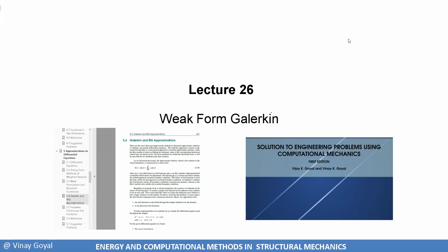In the Rayleigh-Ritz method, we make sure that the approximation is sufficiently differentiable in the functional, basically sufficiently smooth, that it satisfies the essential boundary conditions, that it is complete, and that the basis functions are linearly independent.